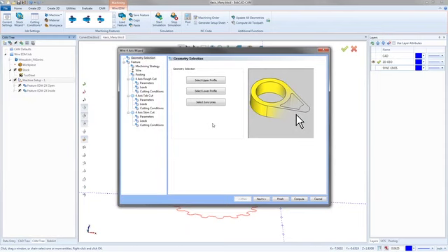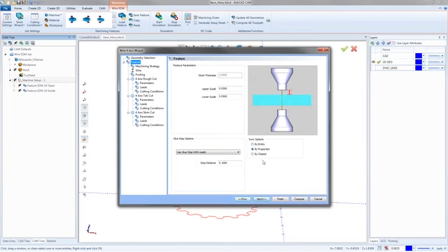Now, for now, I'm going to leave the sync lines off of it. We have every sync line we need, and that should be good enough for us. But I'm going to leave the sync lines off for now because we have some syncing options right here. Now, these are not always going to be the best options to use. Sometimes drawing your sync lines is a much more consistent and just a better way to go all around. But we'll go by entity first. We'll see what kind of cut we get. So syncing by entity means it's going to look at the total number of entities and determine where we should be syncing based on the amount of entities. In theory, this should work really great because these two parts should have the same number of entities, but it's not usually the option I use. So we'll go with by entity for now.